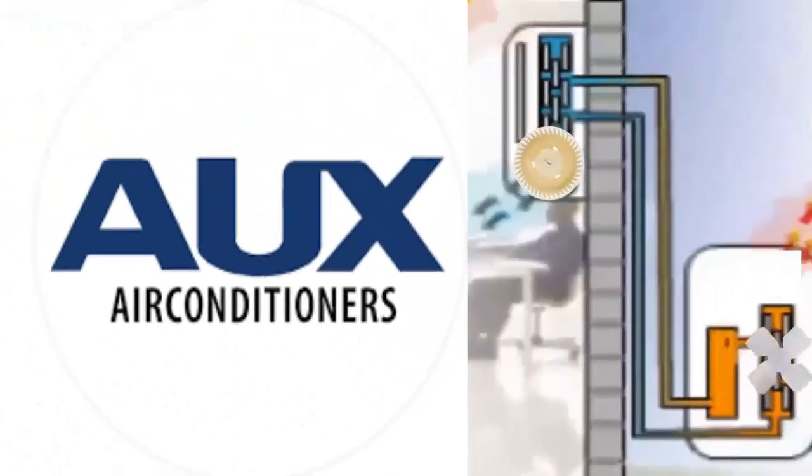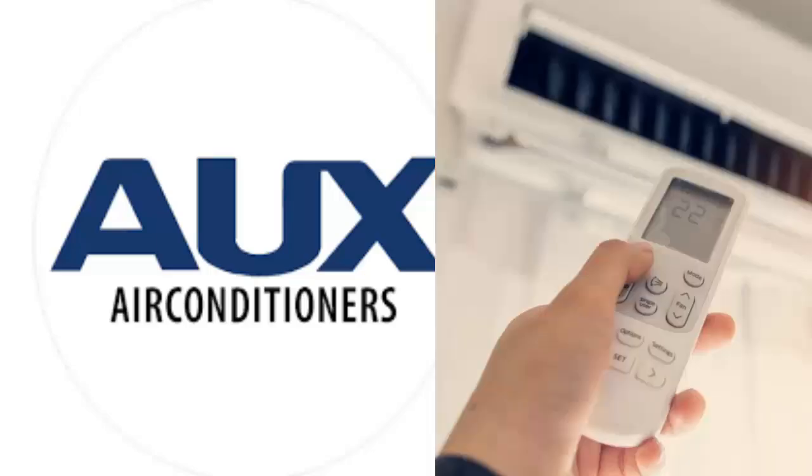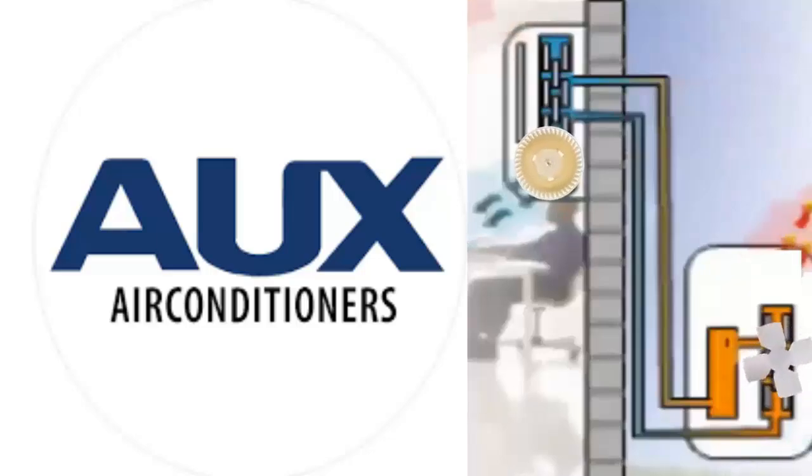Steps to resolve issues with temperature sensors. 1. Turn off the air conditioner and disconnect it for several minutes. Then, turn it back on to check if the error persists. 2. Locate the involved sensor according to the error code.